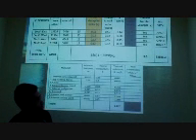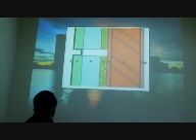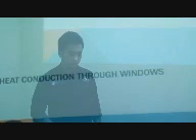Okay, after we decided on our U value and the solar absorption factor, we calculate the OTTV using the formula, and the overall total wall OTTV is 33,583.2. Okay, this is the cross section of our wall material.